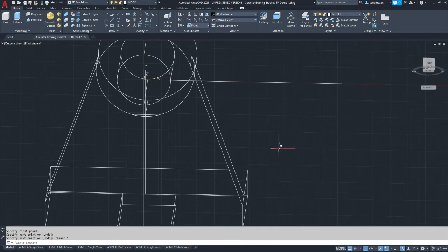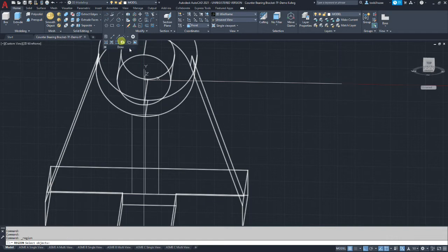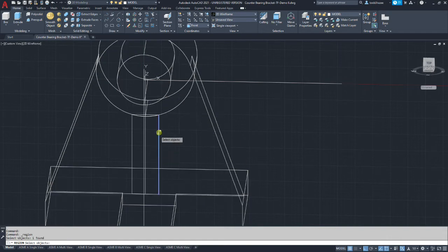We will then make a region out of those elements. So we're going to go to draw, and we're going to create a region of the width of the web, the base of the web, and the little piece of arc we have. Leaving the line is just a construction line to be used in the future if we need it. We're going to accept those as our region,